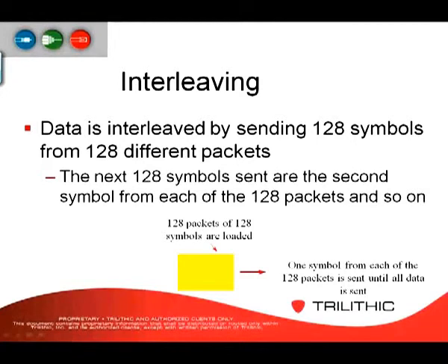So data is interleaved by sending 128 symbols from 128 different packets. The next 128 symbols sent are the second symbols from each of the 128 packets, and so on. So you can notice how the packets are now spread out more, or the symbols are sent from packets that are spread out, and it's a better chance for corrections to be made.